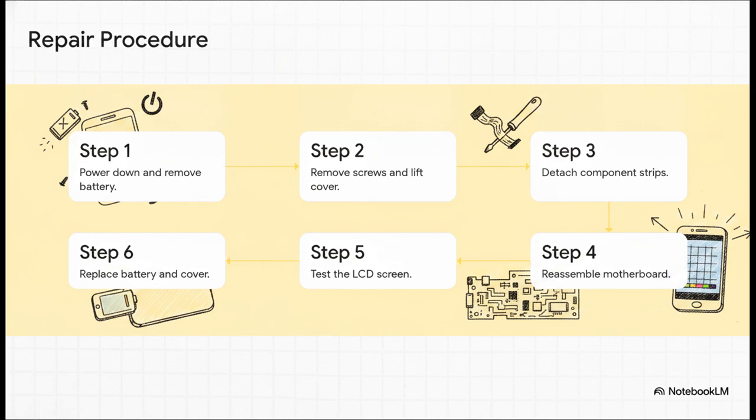Now, crucially, this is step 5, we test the LCD screen before placing the final screen. You never, ever want to glue everything down only to realize your display is unresponsive. Finally, step 6, replace the battery and its cover.